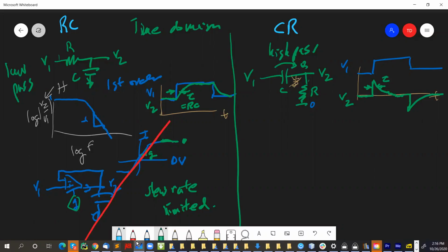Just do exactly the same thing, right? I'm going to draw it down here in blue. So we have the same circuit, V1 here, input capacitor, and now we need some amplifier here that drives this point with the conductance, just like we had before. We're going to connect it up so that the output is connected to the minus input. Now this can be some reference voltage, Vref. There'll be some fixed reference voltage, and then the output is V2 here. And now the resistance, if this has a transconductance G, then the resistance will be 1 over G, 1 over the conductance.